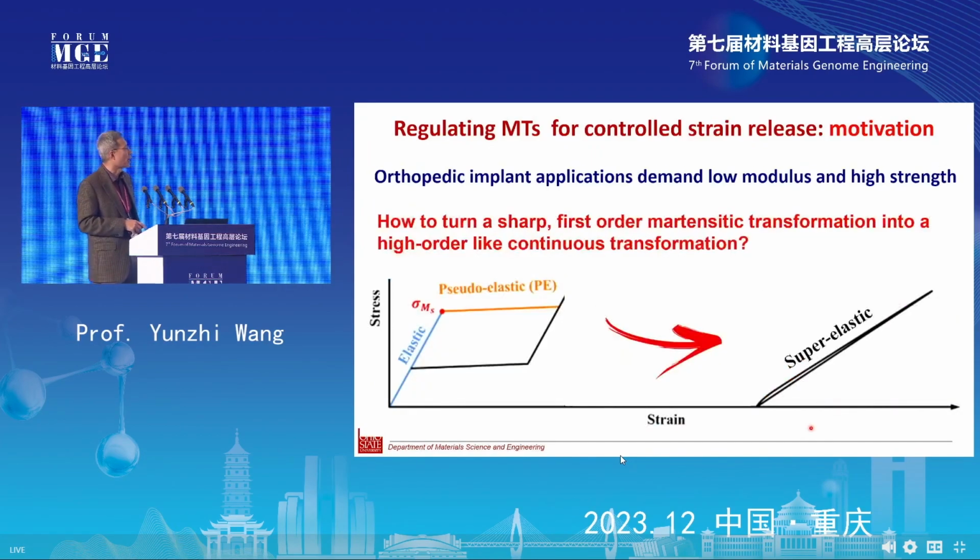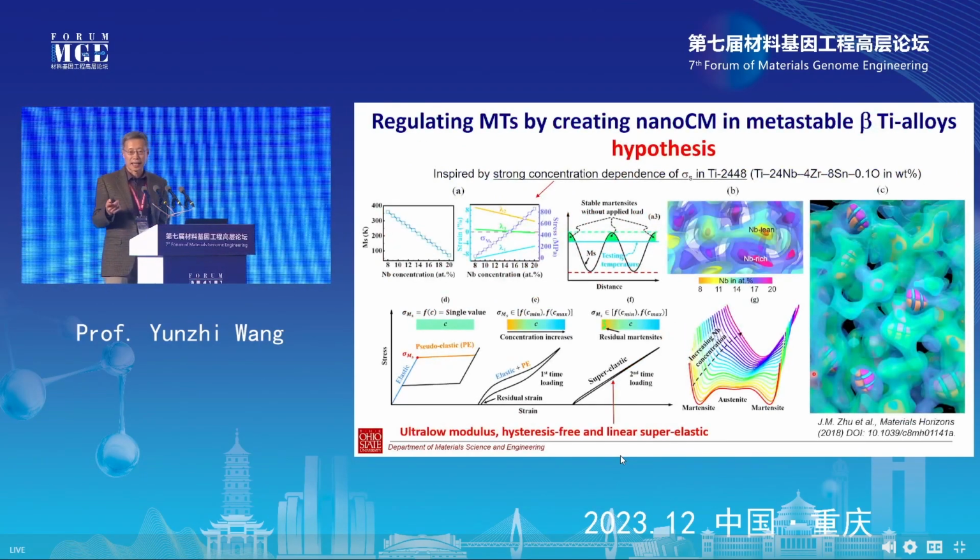So in this regard, we cannot utilize the intrinsic elasticity of the material, but we have a good opportunity if we can utilize the pseudo-elasticity of ferroelastic materials. So here is the stress strain curve that I showed you, with the strain avalanche. But if we can find a way to control the deformation behavior and convert this stress strain behavior into this one, that's the goal, and we can realize low modulus superelastic metals. So that's the goal, and here's the idea.